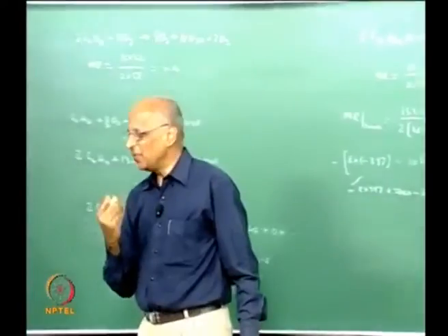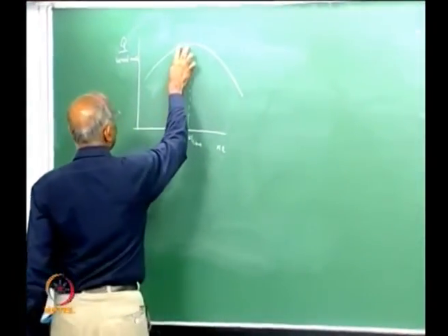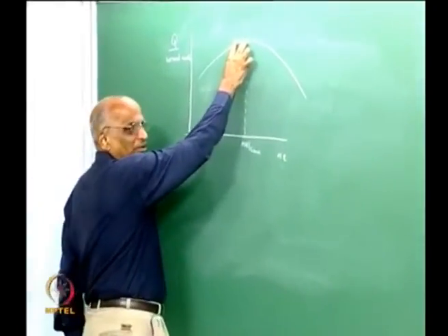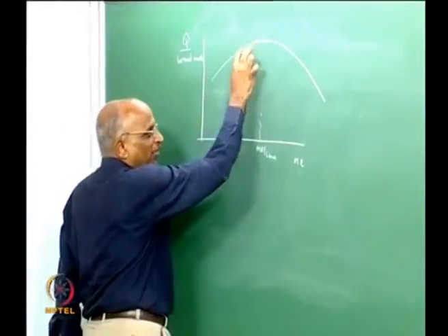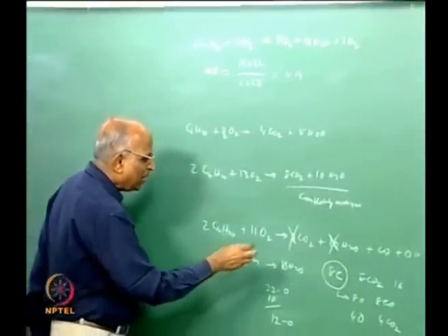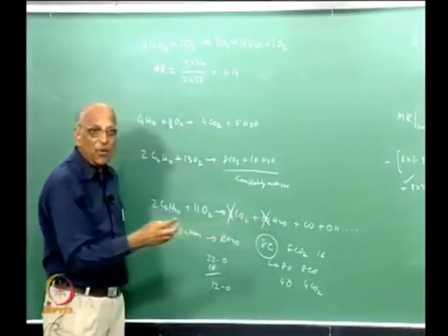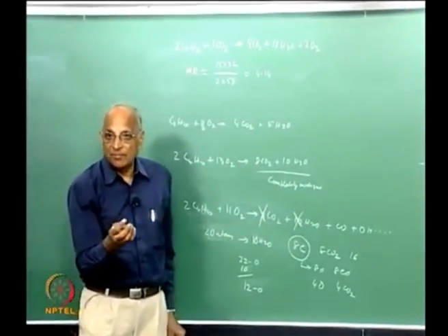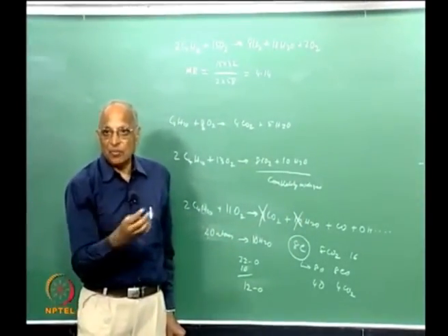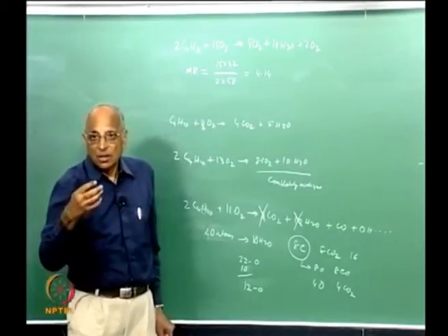But there is a subtle difference. When I look at specific heats of substances which are formed under slightly fuel rich conditions, you are forming substances which are a little weaker, CO instead of CO2, and we found that diatomic species have a higher value than monatomic species, and triatomic species have still different values.